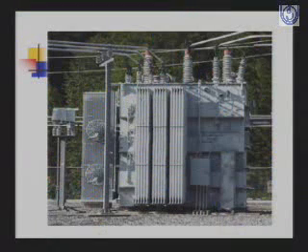As you know, the problems associated with low voltages are that we have higher losses, we have a low voltage profile, and we cannot maintain the voltage at the consumer end. In today's day of regulation, we have to maintain plus minus 6% at the consumer terminals, but we would not be able to do this if the voltage from the grid itself is low. So the tap changer helps in maintaining the voltage at the desired level.